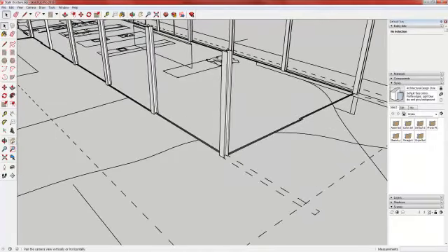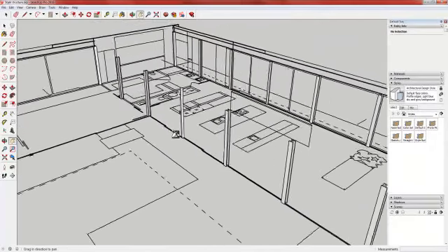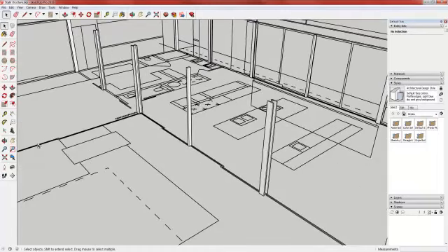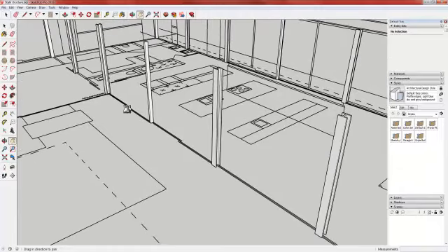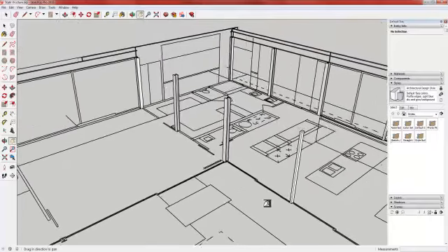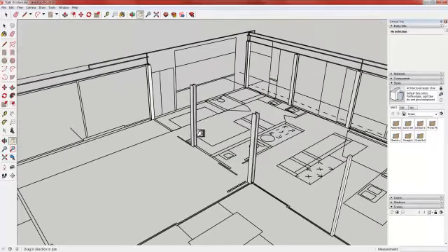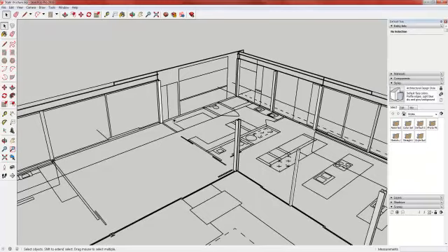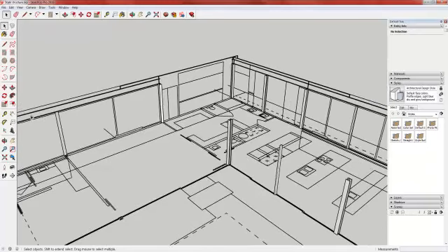And now I've got columns running on one side of my building. And we have our little block that goes between our glass doors. You can see by the line work in the bottom of the drawing that there's two doors here, and these are solid glass infill panels on the other side. And one thing that is a little wacky is we don't have a big column right in the center where the bathroom and storage and pantry area are. So we'll delete that column out, and I think we're in fairly good shape.